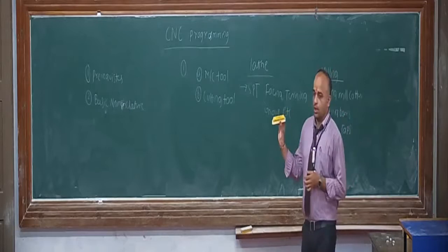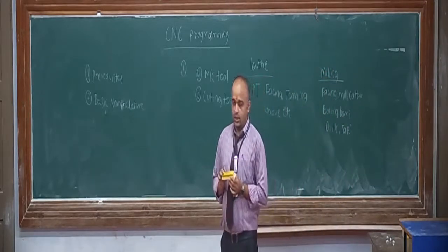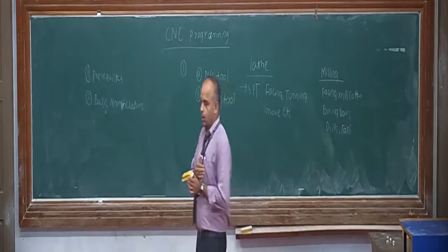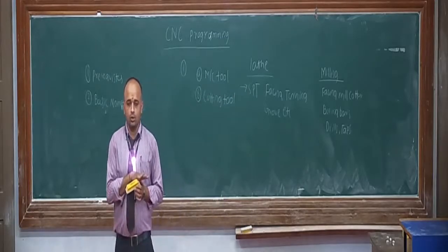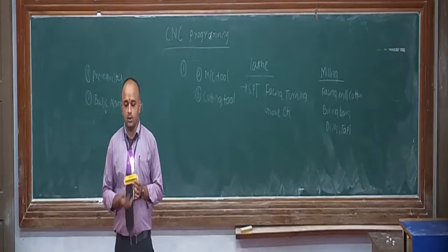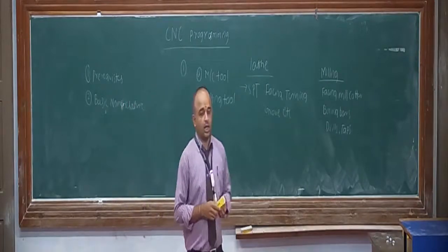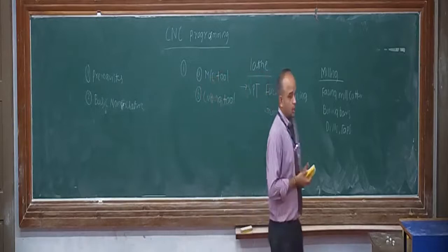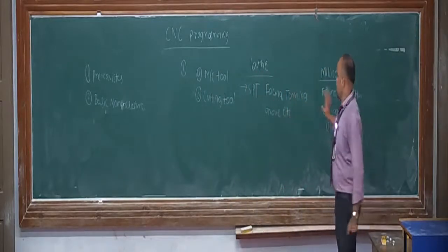Suppose for the workpiece to do all the operations, I require 10 tools. In this condition, what happens? Only 4 tools can be put in your tool holder. After that, the worker has to stop, put in new 4 tools, complete the operations, and again put in new 2 tools. So there are 3 setup times, by which the processing time for the component is reduced. So in order to enhance production, we need to see how many cutting tools a machine can hold. This is in case of lathe.